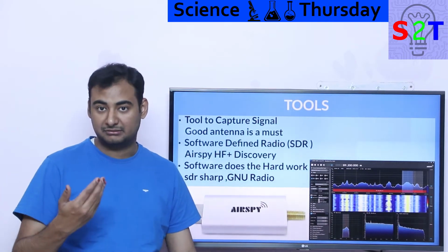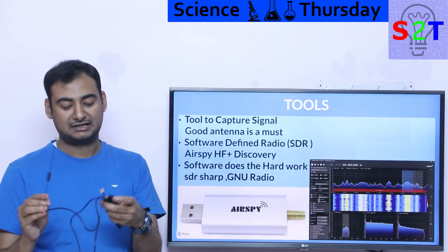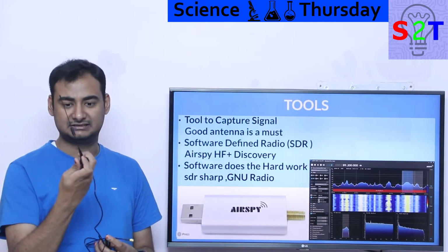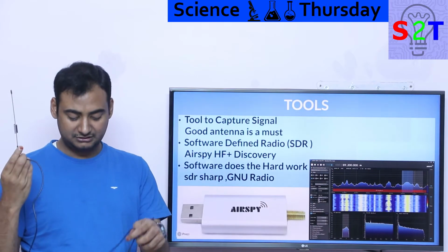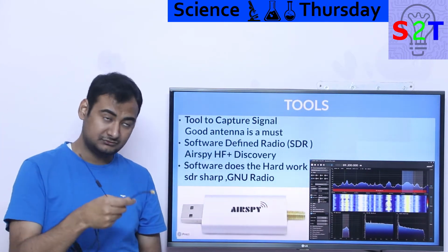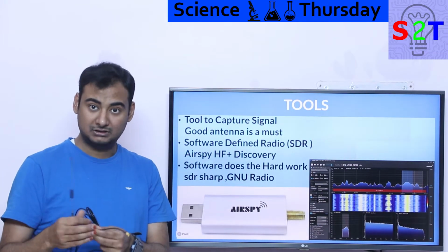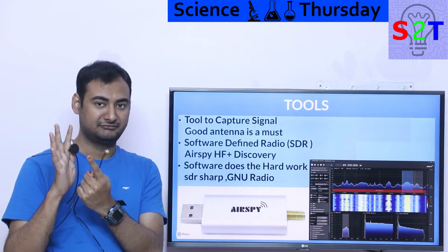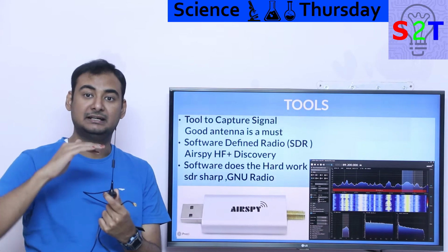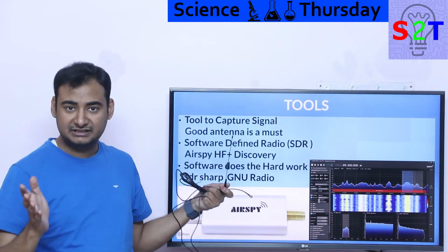And if you are not comfortable buying those sort of things, you can buy antennas that come with SMA jacks directly, but be mindful, these are generally very expensive and very small. This one cost me around 500 rupees. That's a lot, although the cable is long, and these are generally car antennas. You can even buy them in car shops, so do check there. You will find it cheaper there than on Amazon. And they're good, they do work, but they need a ground plane. Be mindful, that's why this magnet is there. I will provide a link for this one and a taller one that is like 12 inches. This is 8 inches. So better the antenna, better the resolution.